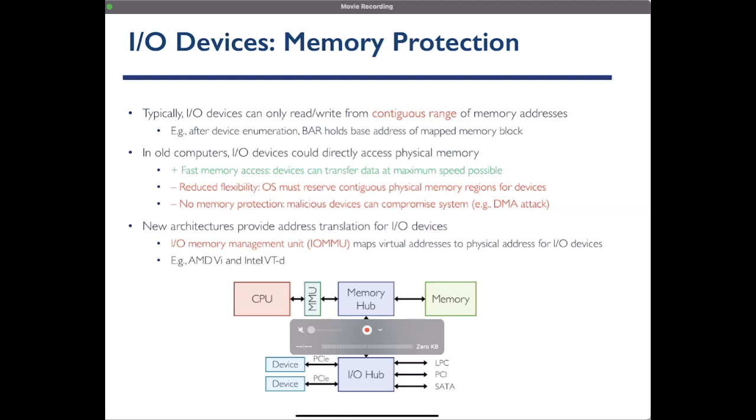You're using physical memory address ranges. So very easy to implement. You can achieve really high speed because there's no need for translation. Let's say you're doing a DMA. Your DMA engine knows a range of physical addresses, and it just writes or reads to that range or from that range.